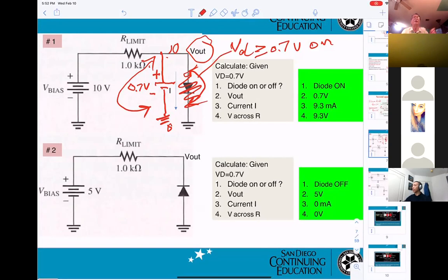You don't care where they connect you. For example, you take the DMM connecting to your car battery. Even if that car battery is connected into the circuitry inside the car, when you measure, you're supposed to get 12 volt, right? I bring that up to make sure that when you measure the voltage across the battery, you must get that battery voltage. Okay? So in this case, the answer will be 0.7 volt.